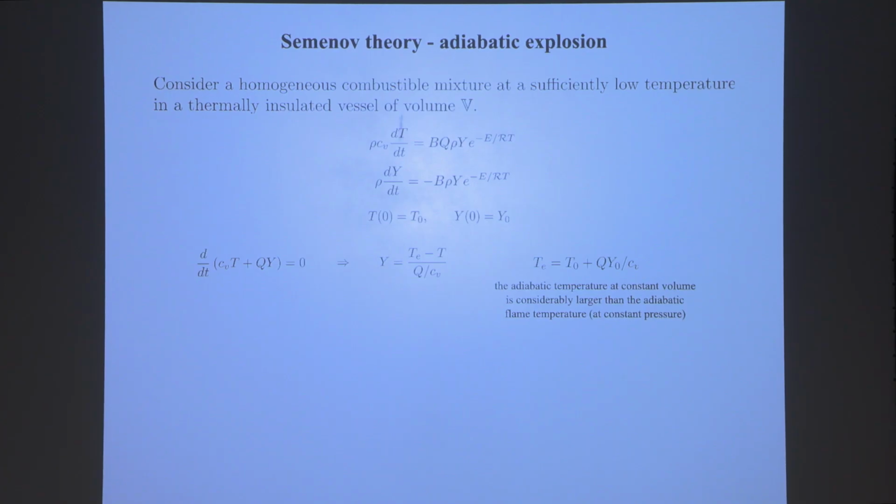And one of the simplest theories is due to Semenov, first of all, under adiabatic conditions, so essentially you have the temperature rising due to the chemistry and the mass is consumed. There is no motion, it's assumed, it's a homogeneous combustible mixture in a vessel, say, or in a region, in a volume.